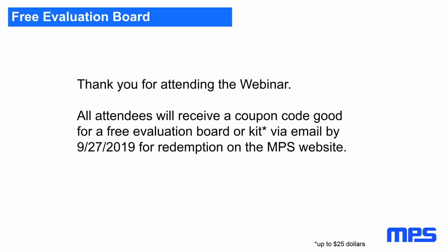I'm not talking about some 500 volt IGBT, but typically a 400 kilohertz or 2 megahertz switcher with a nanosecond or 2 nanosecond fall and rise times. You will have edges which go into the several hundred megahertz areas. So up to 30, 50, 100 megahertz, you won't see much improvement with slowing down the edges.